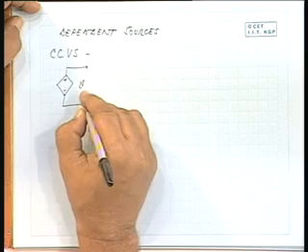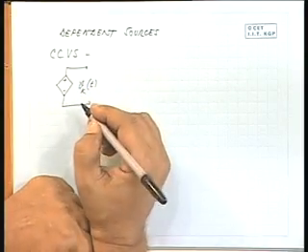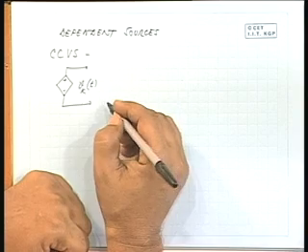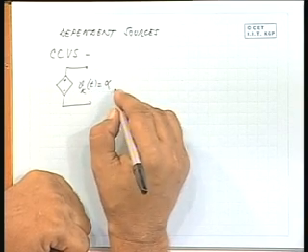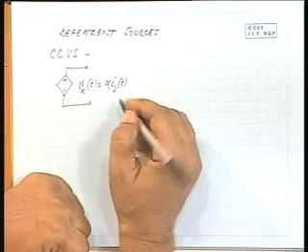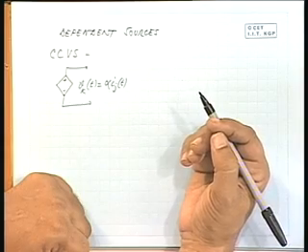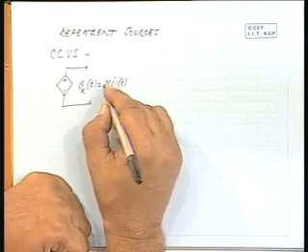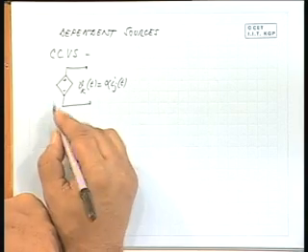This voltage for this kth source is proportional to some current through some other branch, that is Ij is the current through some jth element in the network multiplied by some alpha. So, this is the terminal voltage. So, this is CCVS.